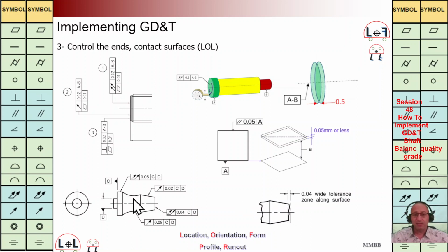We can see we are going to have reference plane, reference axis. We have used this total run out. We are going to have a common axis between A and B. Again, we can use total run out. That's why it is good to use total run out in comparison with perpendicularity.